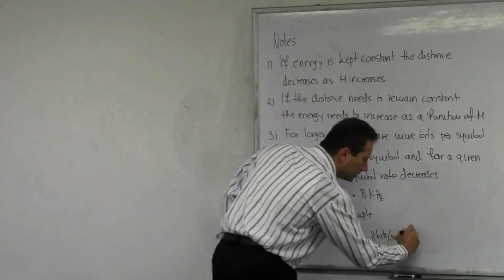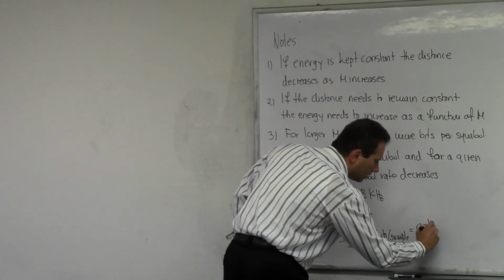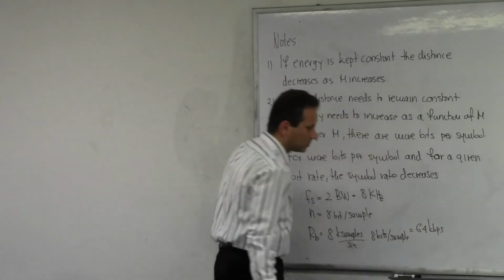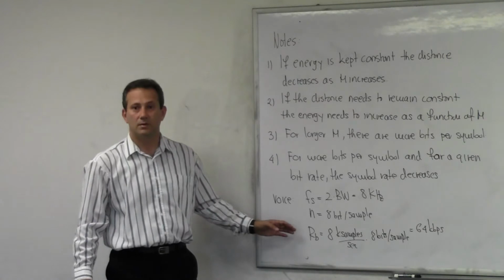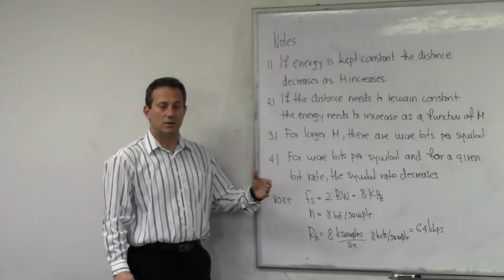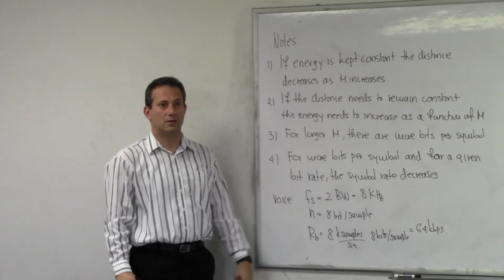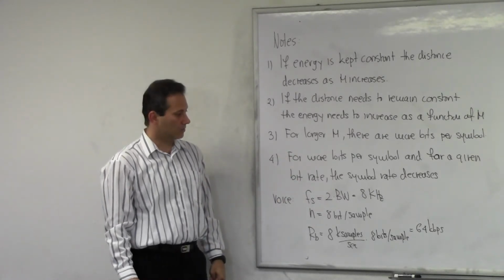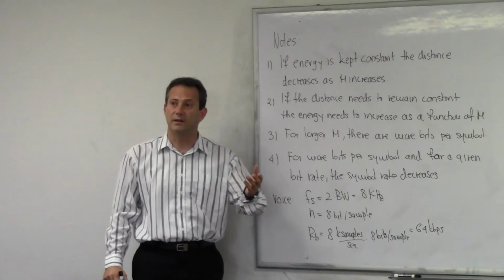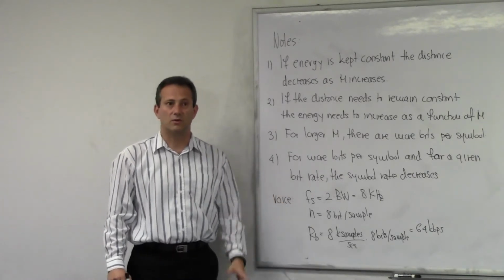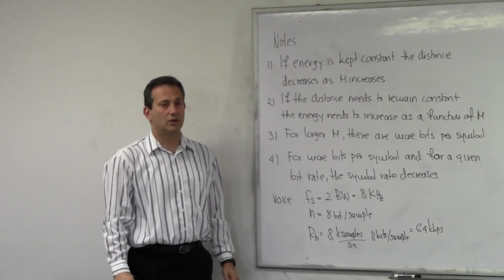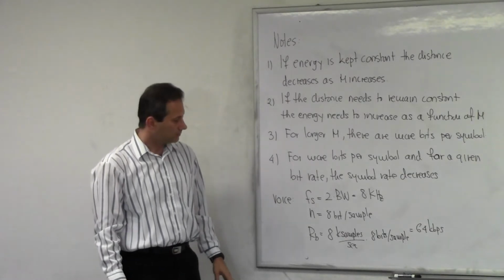And this gives me a rate of 64 kilobits per second. So this is telephone voice. Telephone voice gives us 64 kilobits per second. You should remember that. That's kind of like a known communication number. All of our landline telephony uses 64 kilobits per second of the data rate to represent the voice.